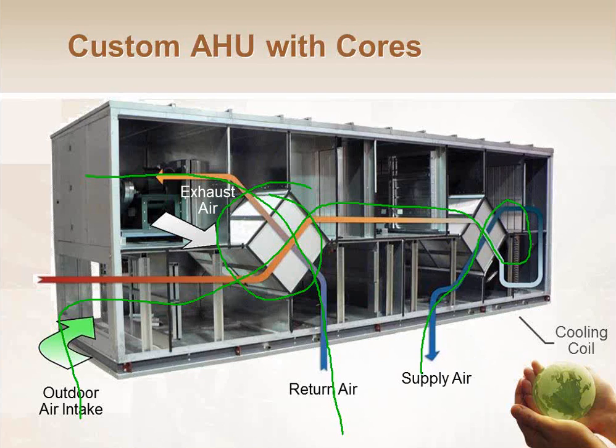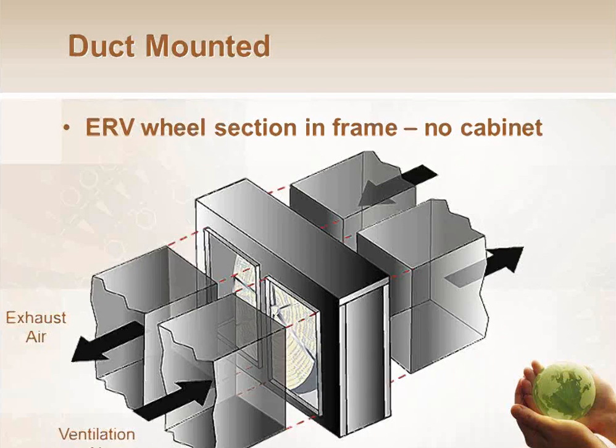So there's my free reheater, very similar to the heat pipe I just showed there before. That air comes through, gives up his heat, gets subcooled, comes back around and picks up that heat so I can heat it back up to a comfortable condition. So that's my free reheat because, as most of you guys know, the energy codes don't permit me to reheat anymore these days. So doing my reheat with hot gas reheat or an ERV core is one way to do that. I could also do this with wheels. Instead of 2 cores here, I could have a wheel here and a wheel here and do the exact same kind of scenario. One for outside air conditioning, one for free reheating when I have dehumidification needs.